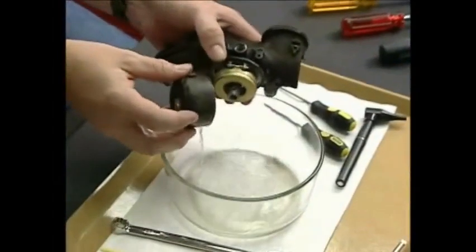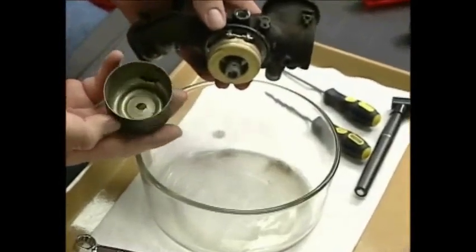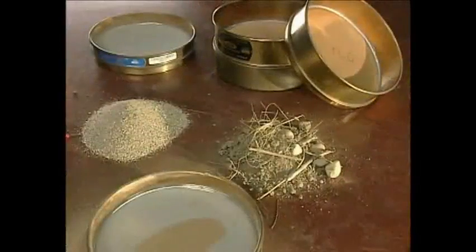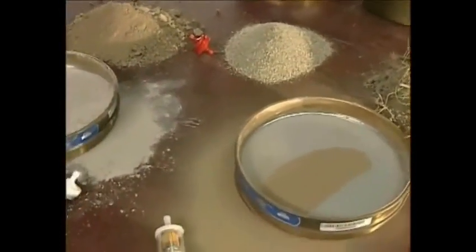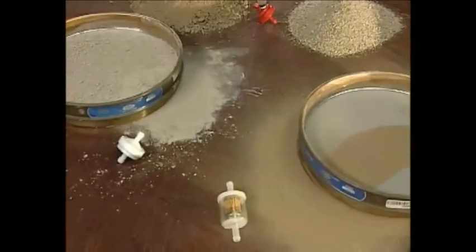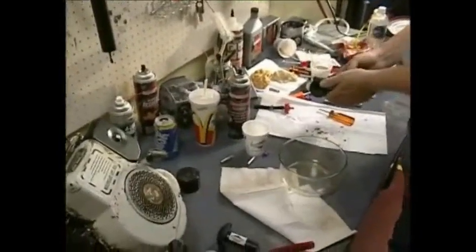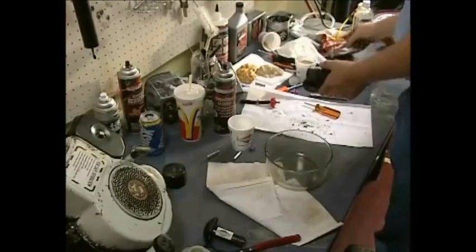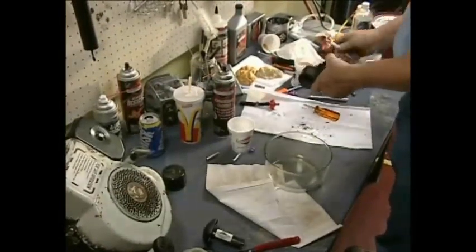Now that we understand what dirt is, let's look at debris. Debris is an unnatural substance, such as plastic, rubber, or metal shavings. When material other than fuel is found within a fuel system, making a distinction as to what the material is and where it was found can aid in establishing how it got there. Sometimes the type of material can even establish who is at fault. For instance, small black plastic chips found plugging a fuel inlet on a brand new lawnmower featuring a black plastic fuel tank may place the blame on the manufacturer.